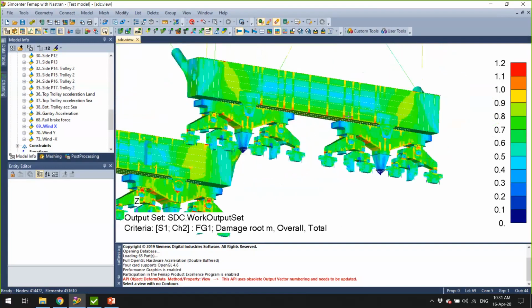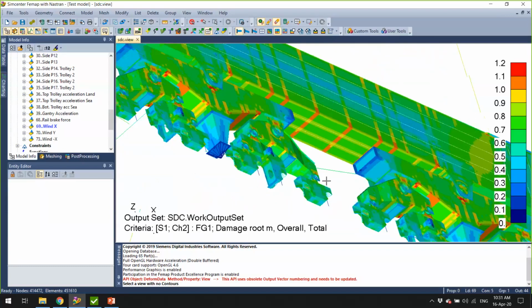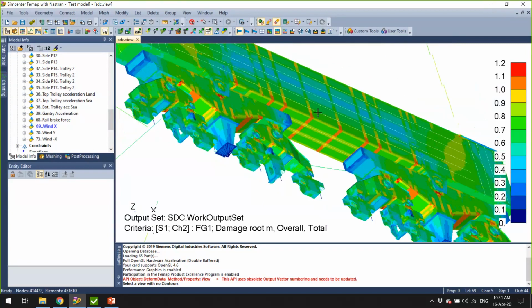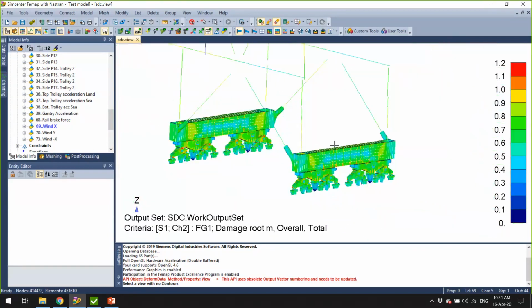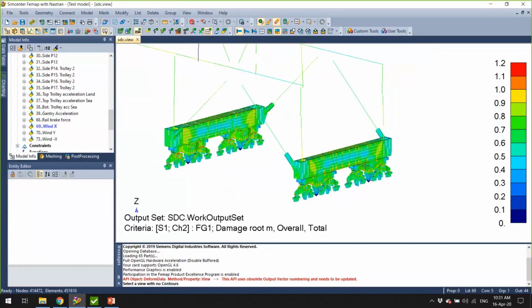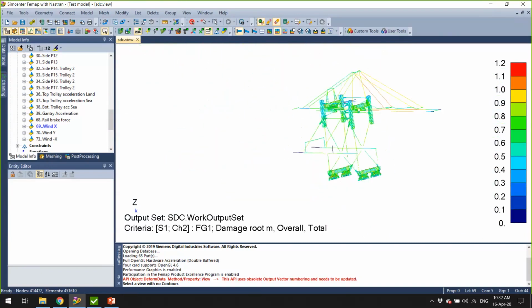And we really see that our classification of weld and setting the proper quality, the real quality of the welding, gives us the best results on the welds. We really see these precise hotspots. We see the overshoots, and we are able to use this for maintenance of our structures subjected to fatigue, or present this during the review of new design or design modifications and any type of calculation that requires the fatigue analysis.